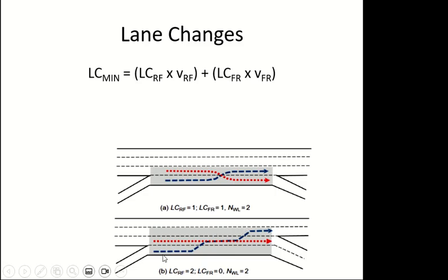Okay, and for this one there is no weaving lane here. There is no lane which I can consider as a weaving lane, because if I am in the auxiliary lane and I want to go to the freeway, I have to make 2 lane changes. You can see the blue line over here. So the lane which needs 2 lane changes to go to the other side is not counted in weaving lanes. Yes, for ramp to freeway you have to make 2 lane changes, but this lane will not be considered part of the weaving lanes.